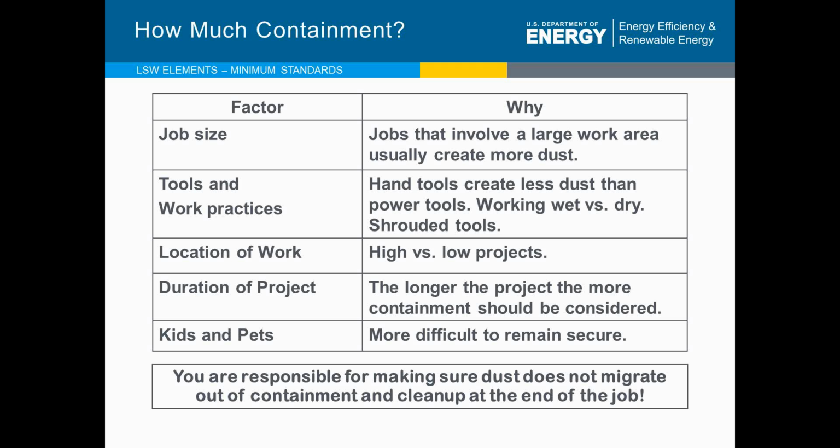The more aggressive tools that we use. Hand tools create less debris, working wet versus dry. If we have shrouded tools, all of these will make a real difference in the amount of dust that's generated. So again, it's up to the certified renovator to know the kinds of jobs that they're doing, the types of tools and methods that they're going to use, and make a judgment as far as how much.